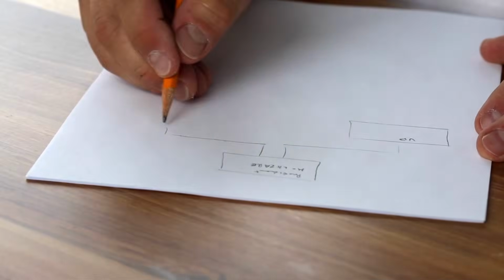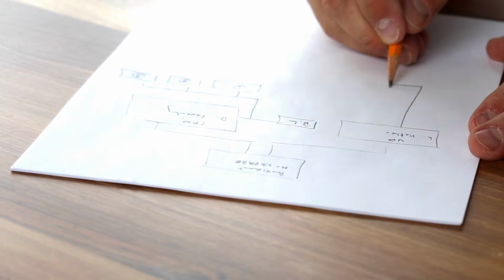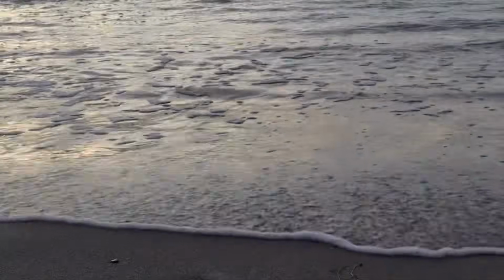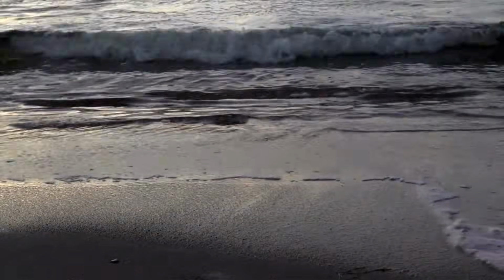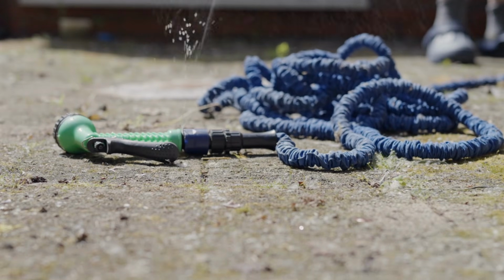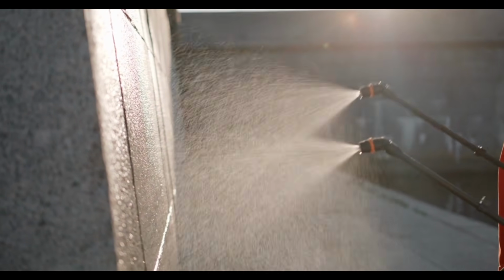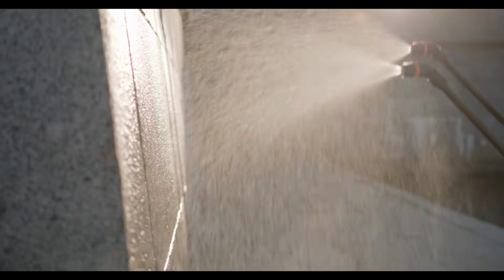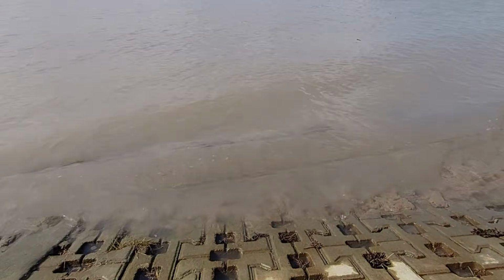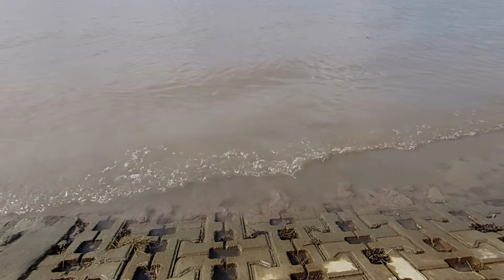In reality, the moment the barrier vanishes, a negative wave, or a rarefaction wave, travels backward into the reservoir, signaling to the resting water that the exit is open. A positive surge wave barrels forward. The physics of this split-second transition is almost impossible to model because the water at the bottom of the dam is under immense pressure, while the water at the top is essentially in freefall. This vertical pressure gradient creates a vertical acceleration that defies the standard horizontal focus of fluid dynamics.